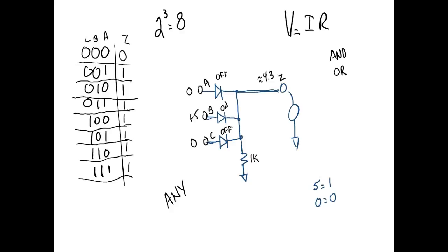Those black ones are what we call rectifier diodes. Those have a slower switching speed. They're designed to turn AC into DC. These are called small signal diodes or switching diodes. These guys are not designed to handle a lot of current. We don't need a lot of current because we're doing logic, right? These guys here switch at an astonishing speed. You just wouldn't understand how fast these other guys can switch.